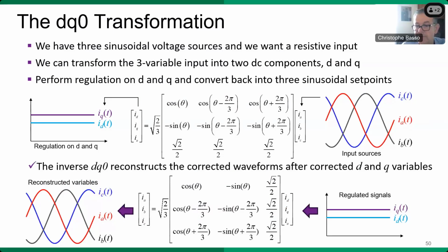In three-phase networks, we have three AC sources, and they are all shifted together by 120 degrees. And we want to ensure output voltage regulation while absorbing a sinusoidal current and keeping the reactive power to the lowest on each phase, or controlling the reactive power in some applications as well, because we shoot for Q equals 0 for the vast majority of cases, but there are plenty of applications where you want to have a different Q and force an impedance to be either inductive or capacitive. So it complicates the architecture.